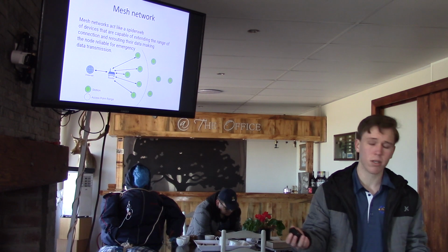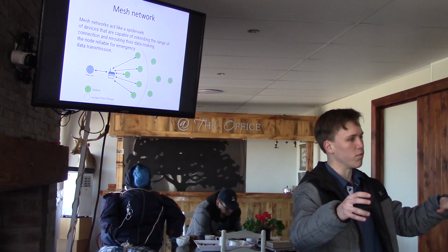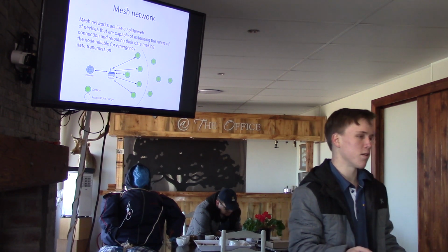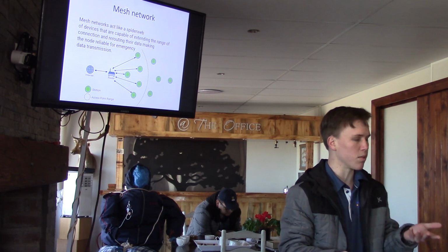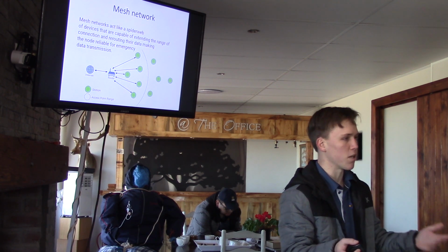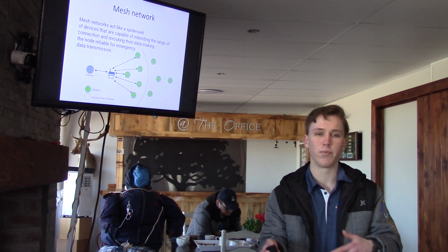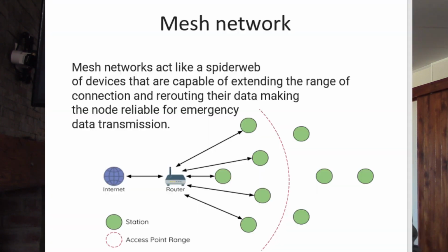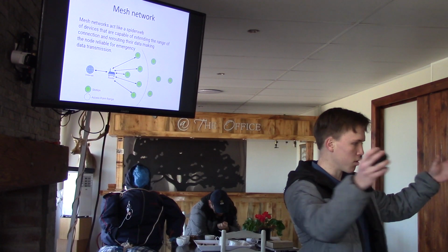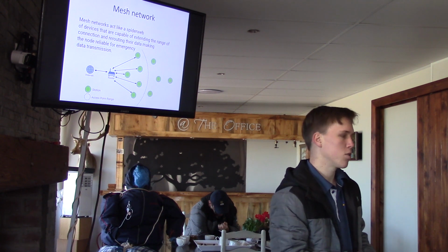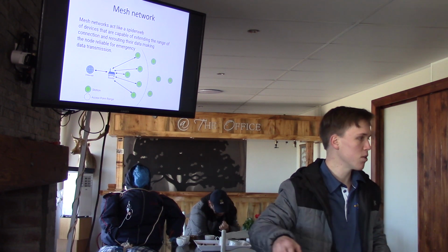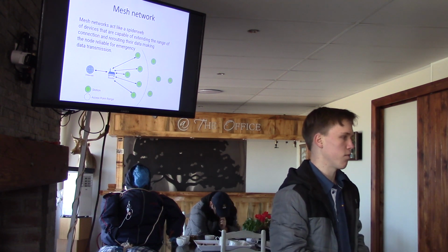Now, what is a mesh network? A mesh network acts like a spider web of devices that is self-healing and self-configuring. Therefore, if you have a mesh network, you can always add more devices, and it will configure itself so that communication is possible. No extra programming needed. Also, something to note is that these ESPs used for mesh networking use the same frequency as Wi-Fi, but do not need to be under a Wi-Fi connection. So you could have a router over here, and they would extend the range of data transmission, even though it is out of the range of the Wi-Fi itself.